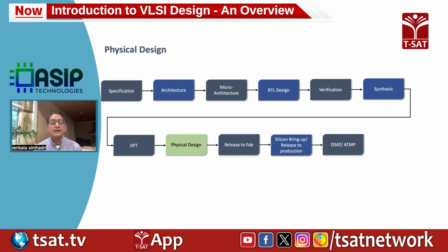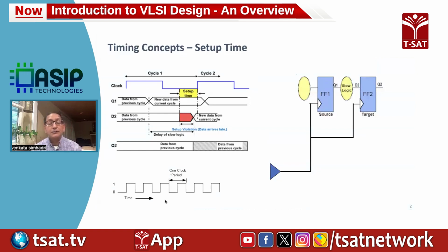The next step in the design is DFT. It's called design for test, followed by physical design. But let me skip DFT for now and talk about physical design. I will come back and cover DFT as the next step. Before we get into physical design, let us understand the timing concepts a little bit. When you are taking a gate level netlist and converting that into a physical design, you have to make sure it meets the performance requirements.